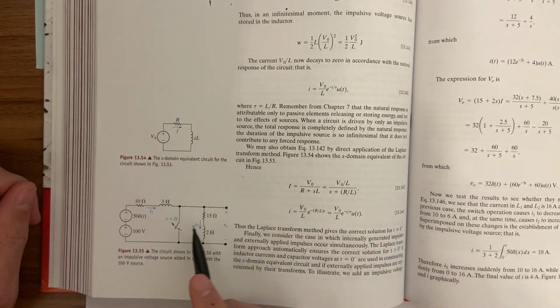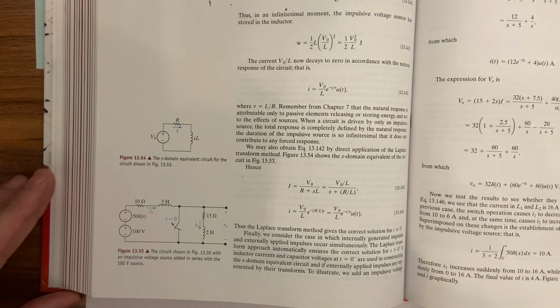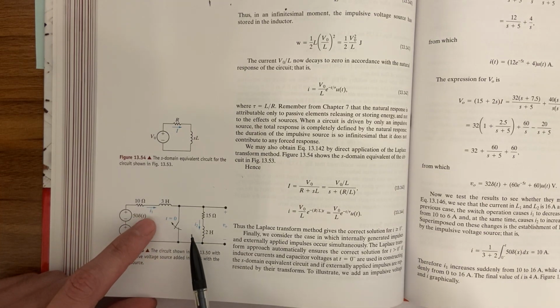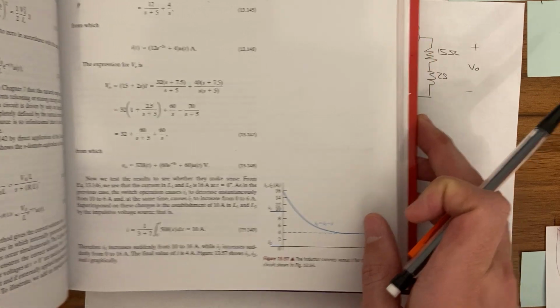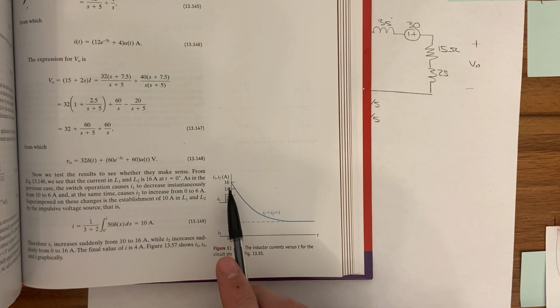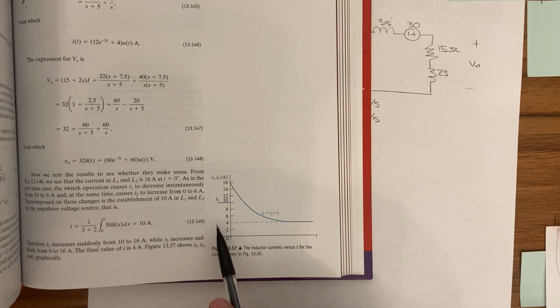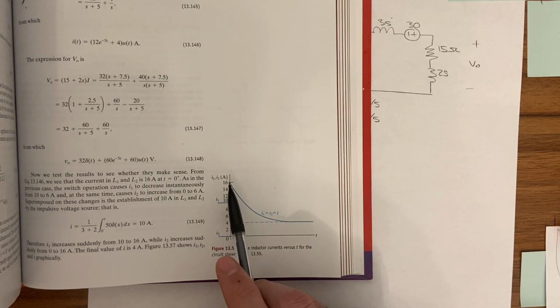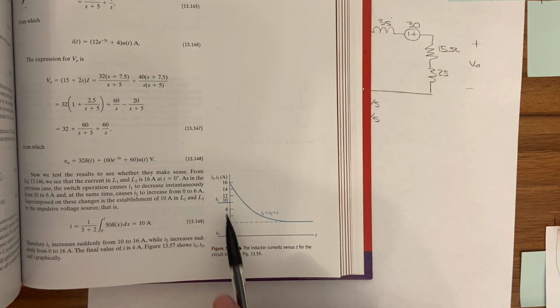Suppose we are interested in I1 and I2, and we want to find the final current after the switch opens. Initially I2 is going to be 0, but there actually is a current right here for I1. If you solve for I using inverse Laplace methods, you end up with an expression right there. But what's interesting is that I1 and I2 combine and jump up to 16, so you have this stepwise jump.